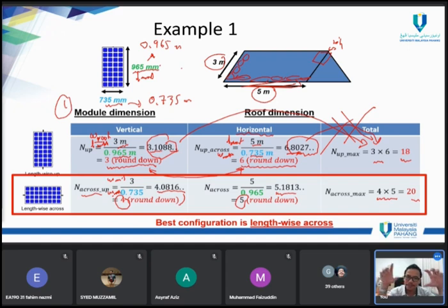You mean the shape or the characteristic? Doctor, the photovoltaic, the silicon layer material it is made of, does it expand in the summer? In most cases, the highest temperature in Malaysia is 75 degrees C. That will not change the physical structure of the modules. Inside also, but the characteristic will be different. For example, voltage will drop.